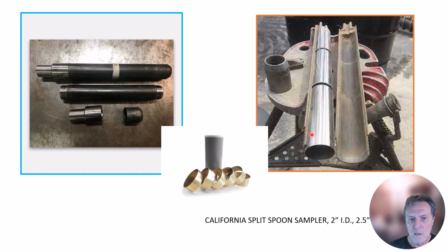In the interior of the tube, you see these steel tubes, which are lined up like so. But more usefully, we use brass rings of 1 inch in thickness for the bottom 6 inches of the sampler, so that when we retrieve the sampler, we have 6 brass rings filled with soil, hopefully, that can then be individually used to run various tests like direct shear, density, moisture, etc.